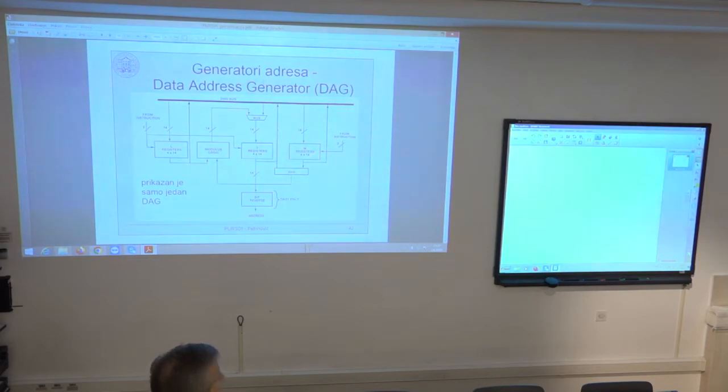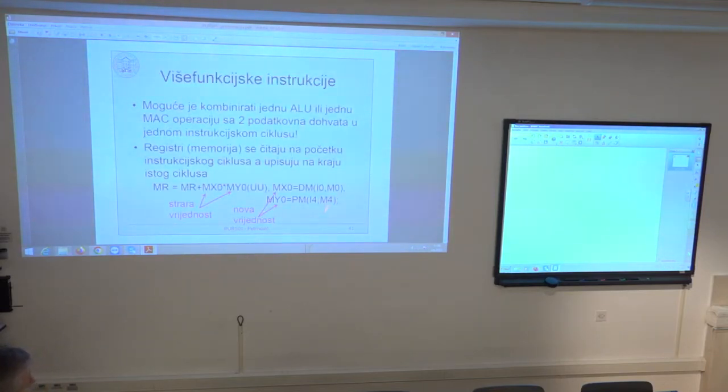For example, if M0 is -1, and I do the fetch with I0, comma, M0, then in this case it will decrement I0 by 1. So you simply store the desired modification values in this set of M registers and invoke one of them after performing the fetch operation by having this comma M0. Okay?